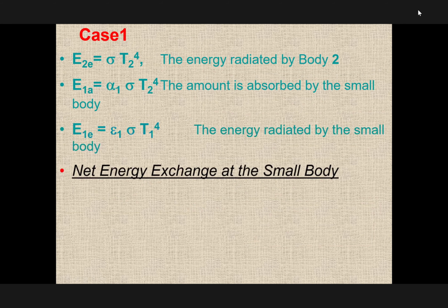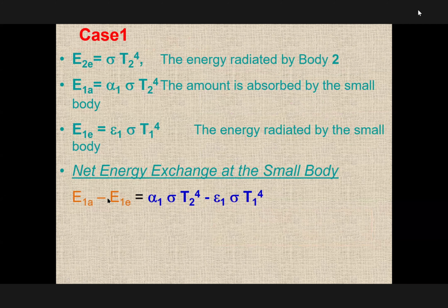And then we can say the net energy exchange for surface one, okay. This one was absorbed. This one was radiated back, emitted back here, emissivity. Therefore, I can write this equation: net energy absorbed by surface one is equal to what is absorbed minus what is emitted. Look at here, this energy emitted by surface two, a portion was absorbed and then emitted back that way, okay?